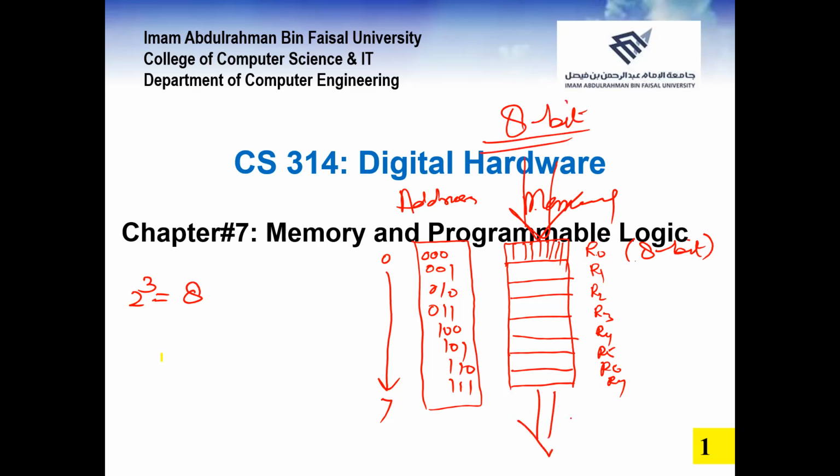Then we'll be having an 8-bit data output line to read the register. So we call this one address lines, a 3-bit address line. We have a data line that brings the data to the register, and one that takes the data from the register. So these are the things which are basically required.